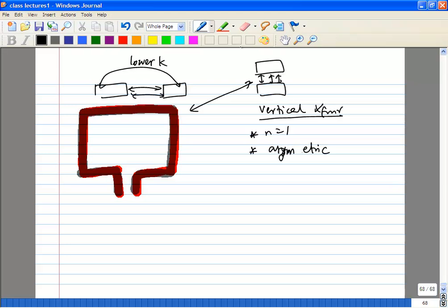Why is it asymmetric? Because the primary is on M6 and the secondary is on M5, right? So there's going to be a difference in resistivity, there's going to be a difference in capacitance, there's going to be a difference in losses, there's going to be a difference in everything. If you are not interested in the symmetry, then this is the way to go.